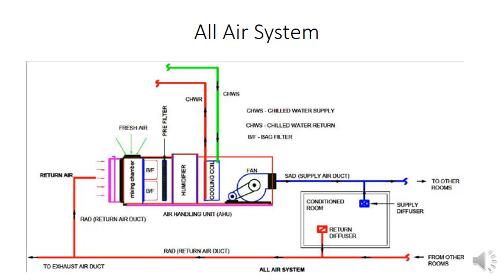Return air and outside air are required to be balanced in proportion, and the rule is supply air equals return air plus fresh air. Since fully treated air is supplied by the AHU, no further processing of the air is required by terminal units in the conditioned space. So this type of device can be used.